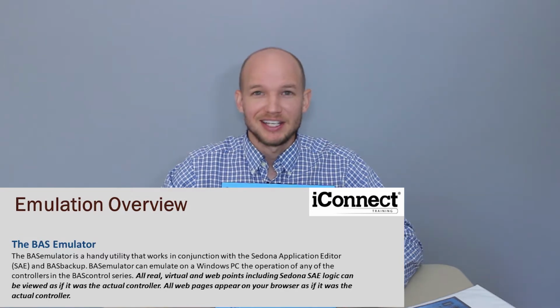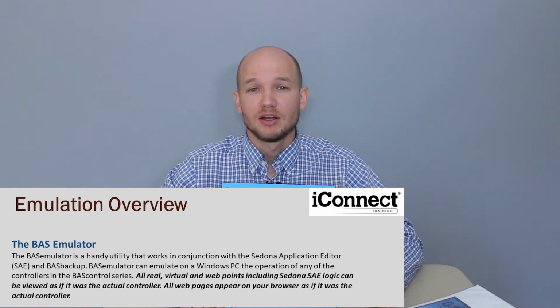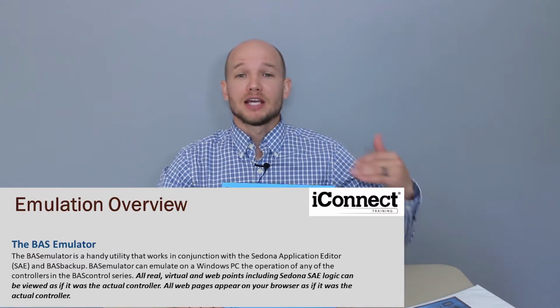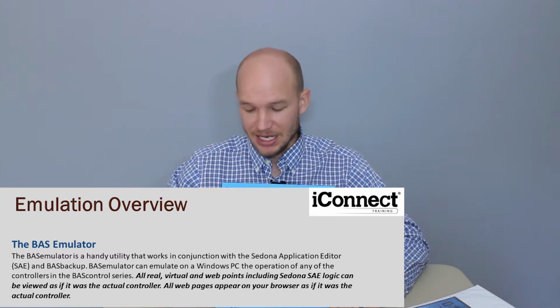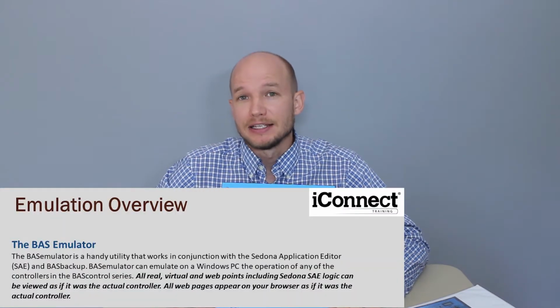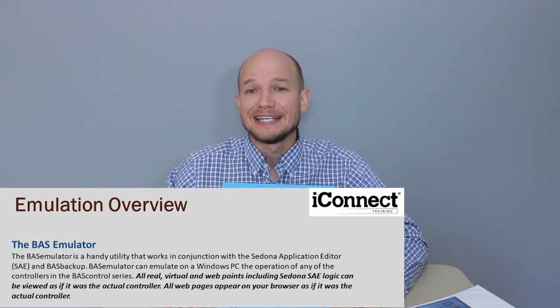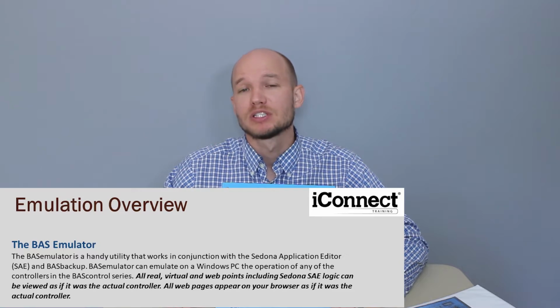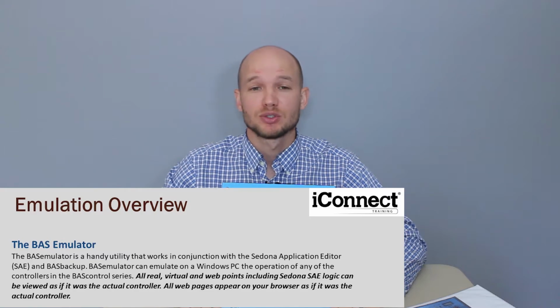The BAS Emulator is a handy utility and a great piece of software that works in conjunction with Sedona Application Editor, also known as SAE, and the program BAS Backup. BAS Emulator can emulate on a Windows PC the operation of any controller in the BAS Control series. So today we're working on the BAS Control 22. This is key. It's highlighted in bold here. All real, virtual, and web points, including Sedona SAE logic, can be viewed as if it was an actual controller. All web pages appear the same as if it was an actual controller.